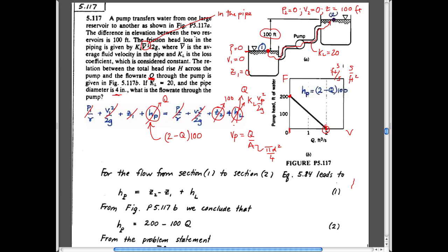Of course, you could write the point 1 at any point you wanted to. You could write it here for that matter, in which case you'd have a pressure term added to it, right? P over gamma, P1 over gamma. But it's just easier to write it on these points. You'd get exactly the same expression with this because if you choose the depth of this tank, you'd know what P over gamma is and you'd know what this different elevation would be, and you'd just be adding it to the elevation difference. So this is Z2, right, at this point. So it allows you to be able to solve it.